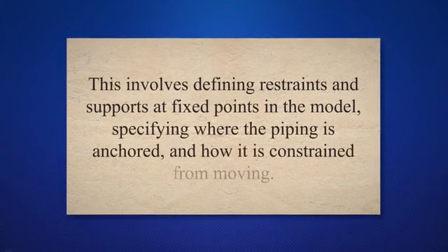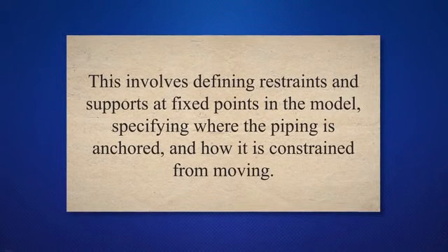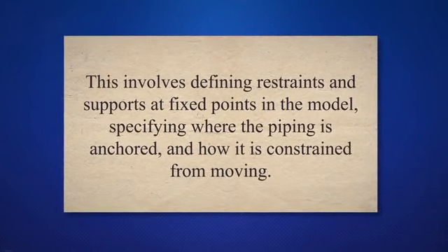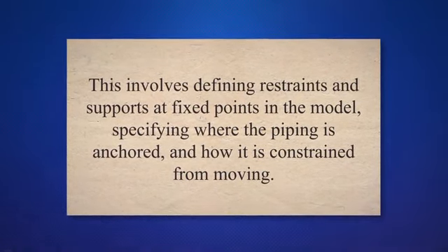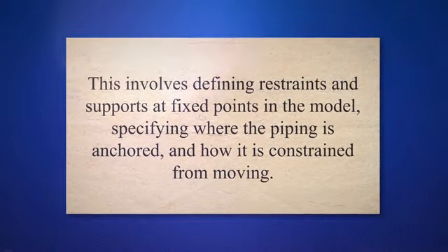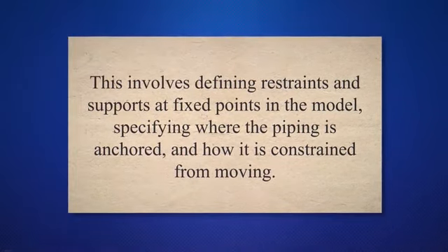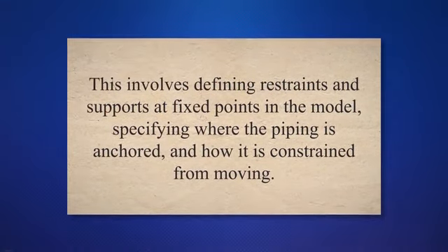Setting up boundary conditions is critical. This involves defining restraints and supports at fixed points in the model, specifying where the piping is anchored, and how it is constrained from moving. Boundary conditions help simulate real-world conditions accurately.